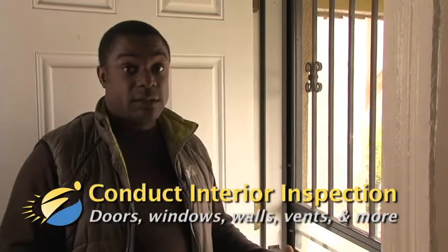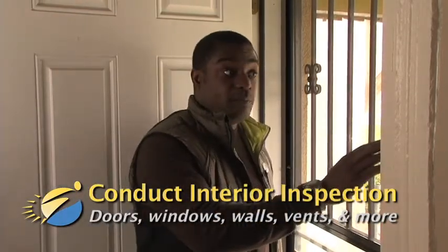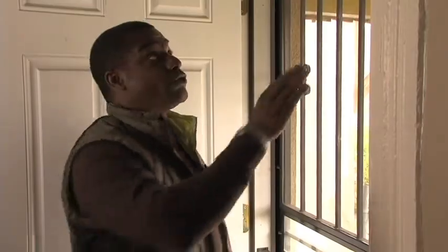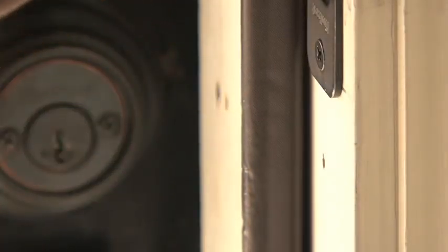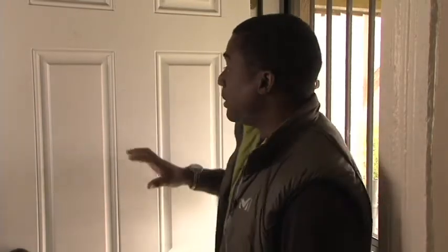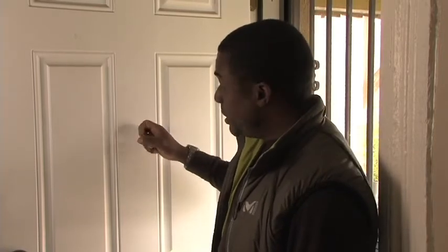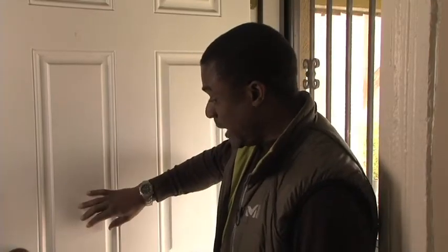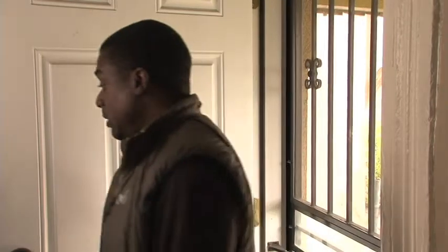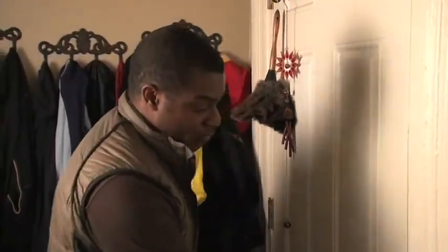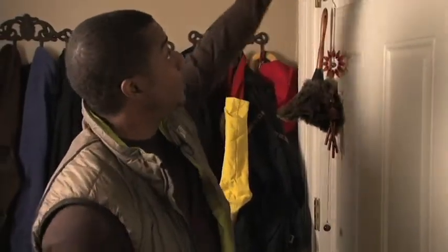The next thing we want to take a look at is the weather stripping for the main door. We want to make sure, first off, that the weather stripping is here. Make sure that it's in good shape and that it's not cracked and it's still soft to the touch. The next thing we want to take a look at is our main door. What is it made out of? Is it in good shape? If it's wood, metal, making sure it doesn't have any cracks or openings or leaks. The next thing we want to do is to shut that main door and check to make sure that we have a nice good seal going all the way around.